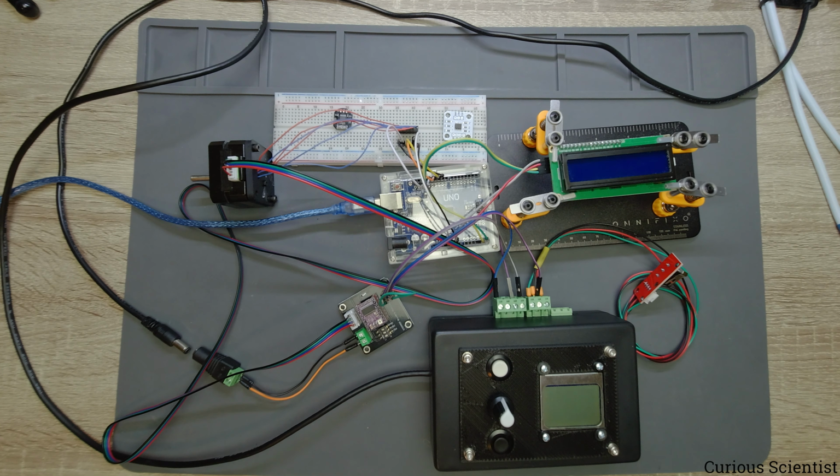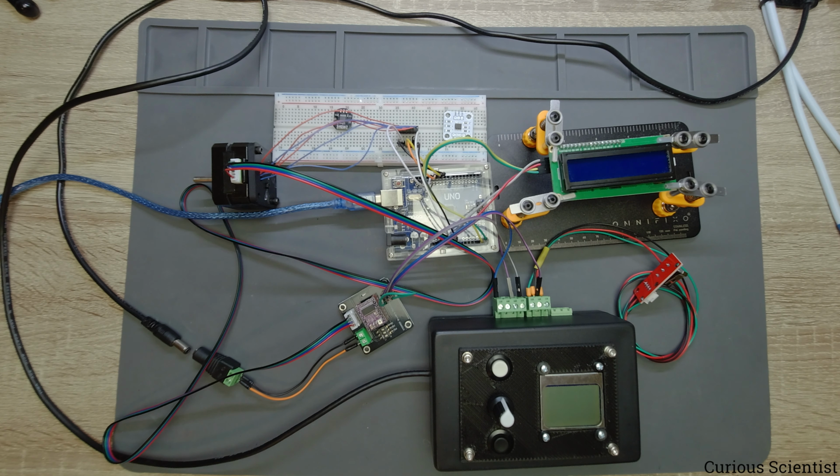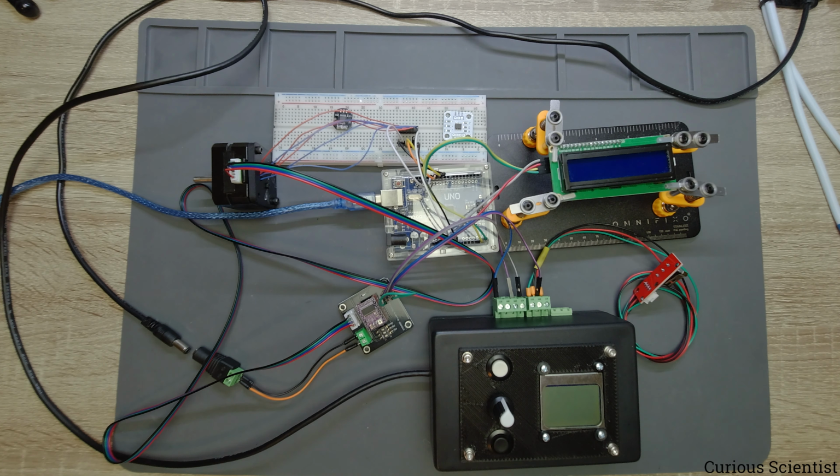Usually when we are using some kind of small stepper motor with, let's say, 400 steps per turn microstepping, which is a relatively general setting, then you are just below 1 degree per step. So you can resolve the steps of a stepper motor easily with both sensors.